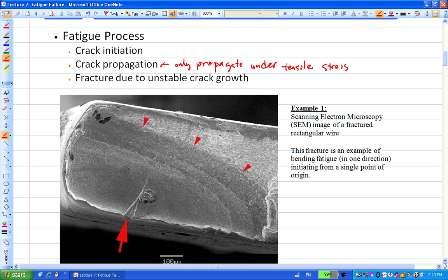The crack becomes larger and larger, until in the end it just cannot endure this stress anymore. That's what you call the last straw on the camel's back. At that stage, you have this so-called sudden fracture. So this whole piece will fracture at this boundary here, and this whole area shows the fracture of this wire, right?